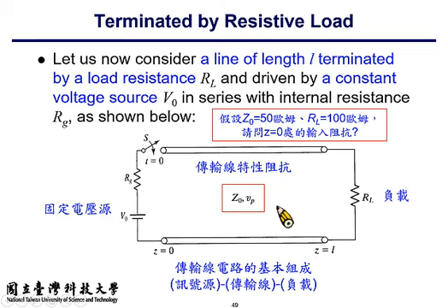However, if you are asking me what is the input impedance observed at this position at time instances 1 second, 2 seconds, 10 seconds, if the time is sufficiently long, then the termination, I mean the resistor placed at the right end, comes into play. Because the signals will bounce back and forth on the transmission line.